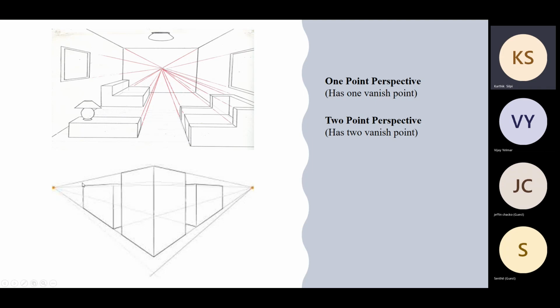And the second thing is you have three blocks over here, and if you are looking from two directions, they will merge in a single point. That is called 2 point perspective, which has two vanishing points. Like say, if you are looking from this angle from here, and your view is extended in this direction and this direction, at some point your view has to end.